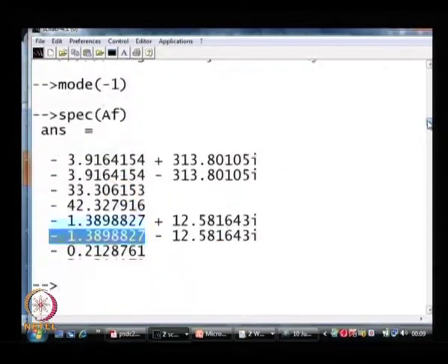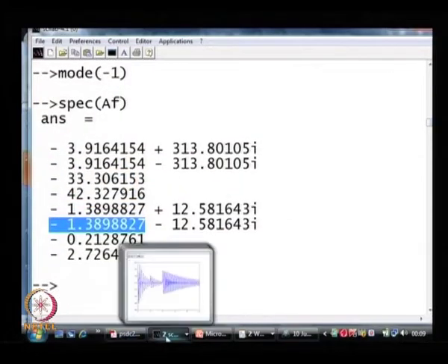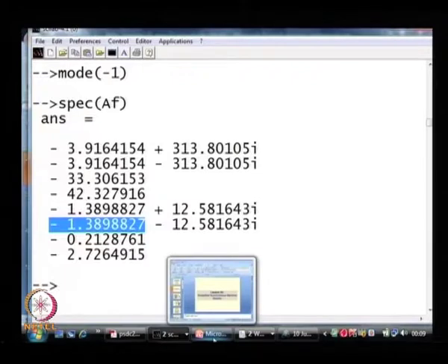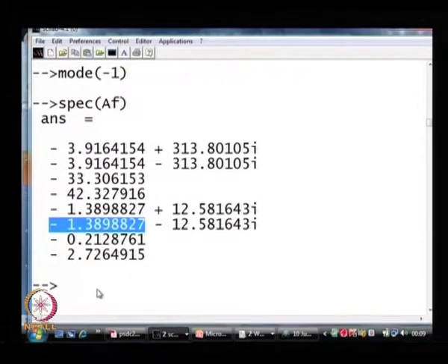So, this seems to be consistent with what we see here. We see a slower rate of decay when we consider a lower order model. Okay. Now, remember here that we are not doing any closed loop feedback control of the field voltage. The field voltage is practically a constant. We are either giving step changes or we are keeping it constant.